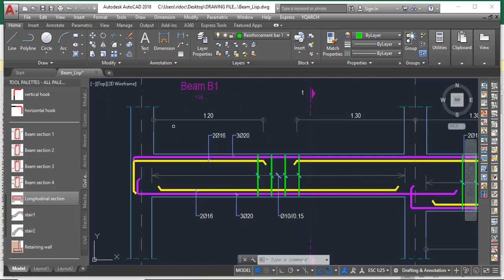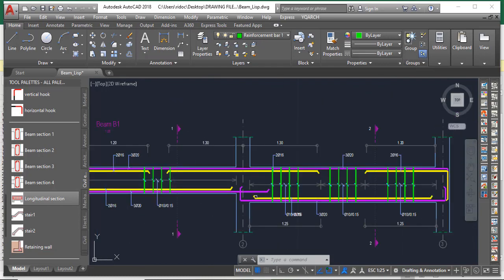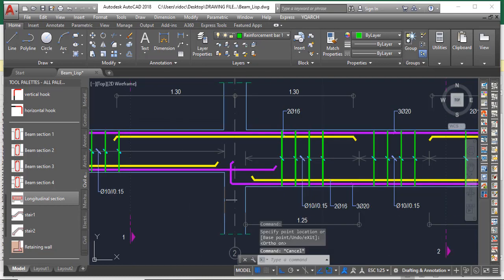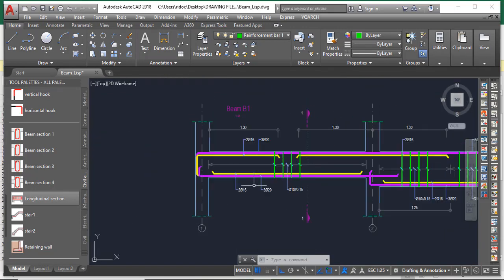You were the one who did all of these changes. So you have all of this as it is, and you can see this is deeper. We use 600 mm change here. Then you can see your link. This is the link at the center, which is 10 mm at the spacing of 150 mm, and then like this. You can also make your changes.